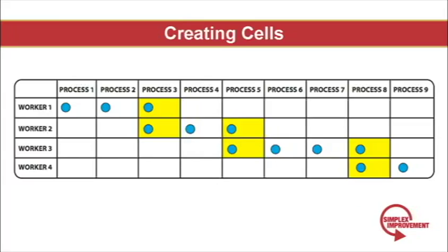Each operator has a designated set of tasks that are represented by the white cells. So the highlighted tasks are those that either station can perform. If the operator at workstation 1 observes the operator at station 2 struggling momentarily, he can help out by completing the shared task. These shared tasks serve as buffers and keep the line running at an even pace.